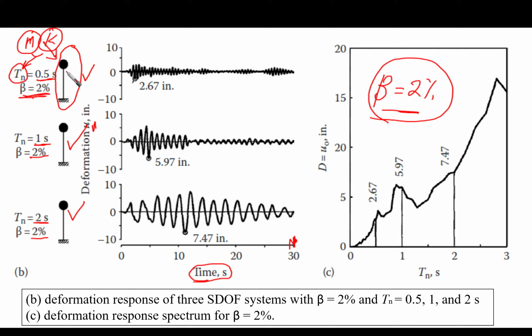analysis for this linear elastic single degree of freedom system, we need to plot the response based on Duhamel's integral and the differential equations that I explained in the previous 2 videos, for each point of time. This would be done for us for each point of time. Along this t, we are going to obtain u, which is the deformation. Then we are going to plot it here.